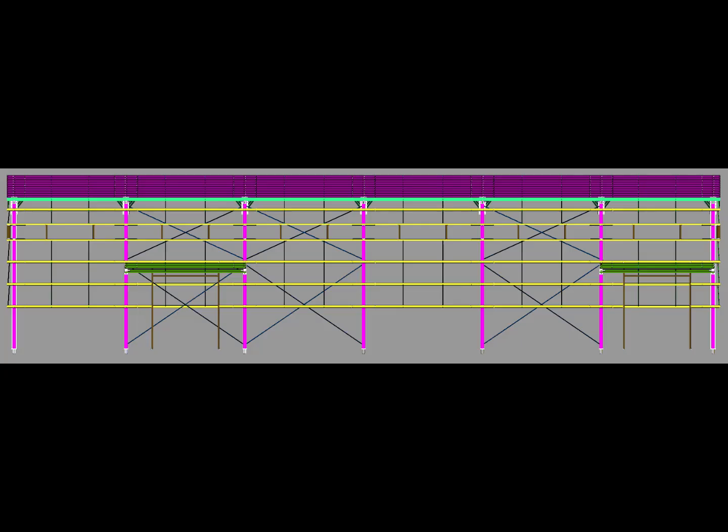Once you develop this habit, reading a complicated PEB 3D model becomes much easier. You can start with the main columns and primary framing. Then identify the secondary members. Then locate the bracing. And finally, identify the smaller members such as sag rods and their connections.